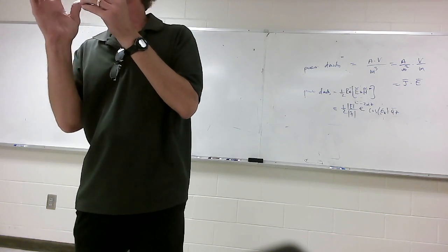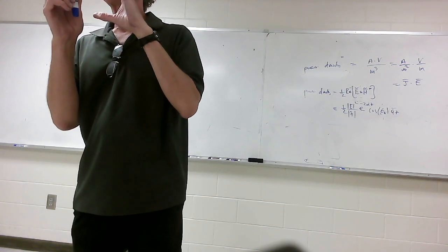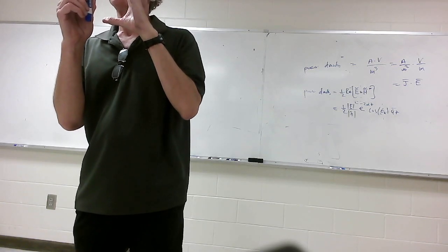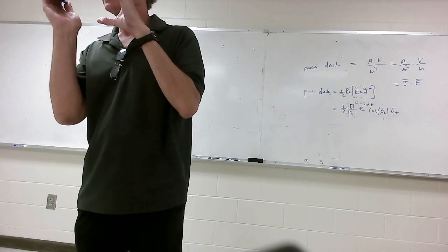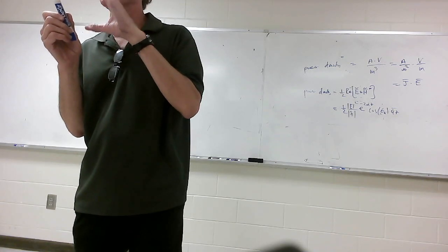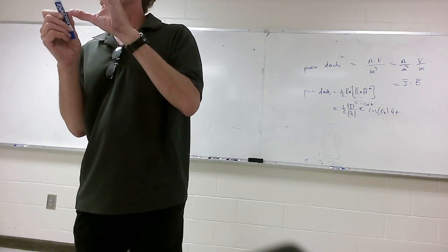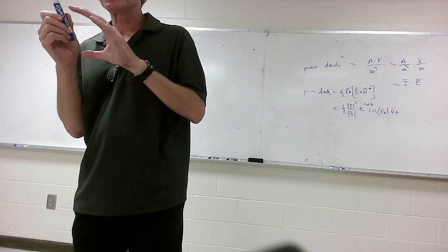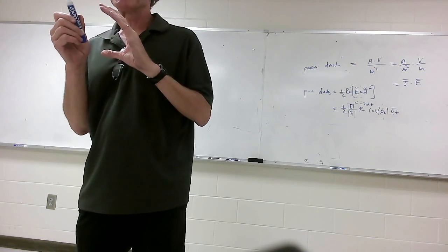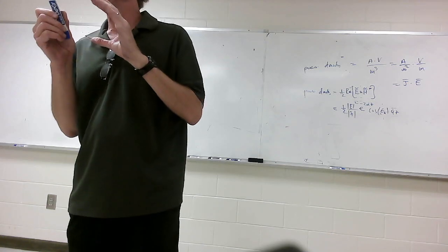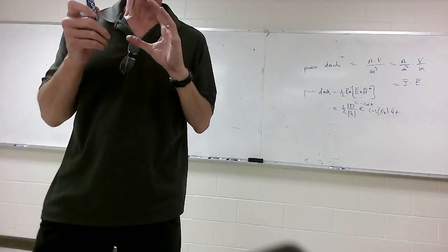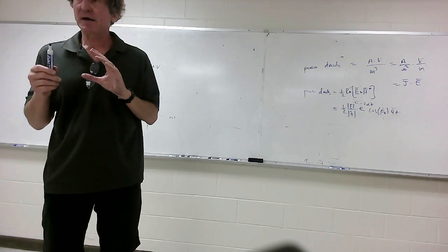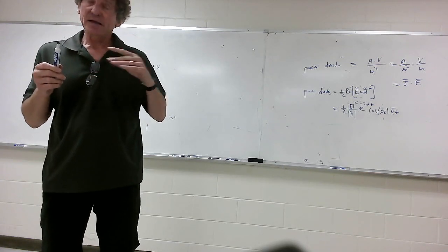That's the nice thing. However, those type of dielectrics have a much lower breakdown threshold, typically, than electrolytics. Electrolytics can have a huge voltage, which makes them nice, and they have a large epsilon relative, so they store a lot of energy. Do y'all follow me on this, class? You can look up electrolytic capacitors. You should be familiar with this because some of you will be working around probably pulse power applications, and you have to know you can't just use an electrolytic capacitor for anything where you could get reverse current through.